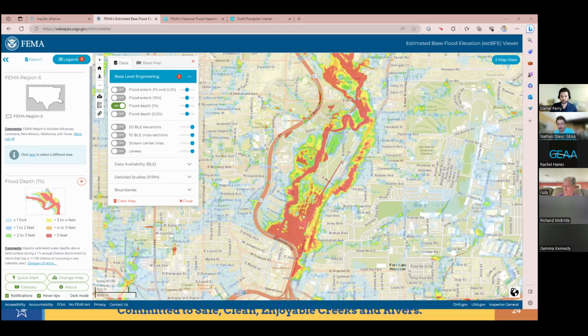I appreciate it. Looks like I have another question from Mark K. Would it reduce the fluvial rate of the canalized streams by eliminating concrete and adding natural landscaping? So the main purpose of concrete, it's kind of an inverse relationship. If you speed up the flow, you're going to start seeing that water surface elevation decrease. So if we were to slow down these flows, you'd have a much wider floodplain.